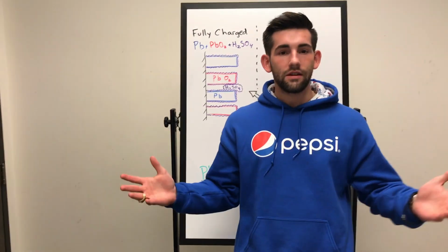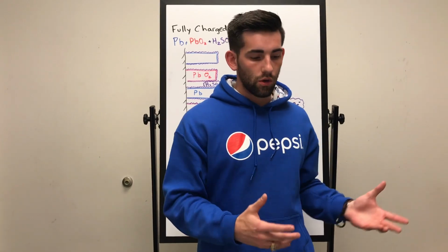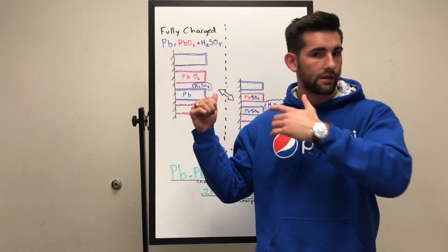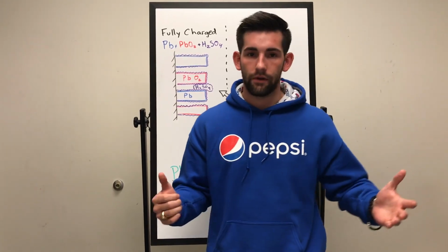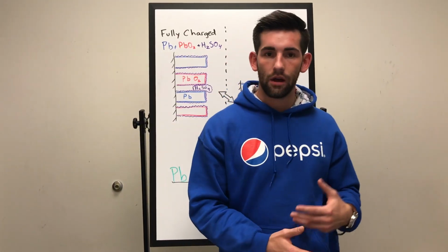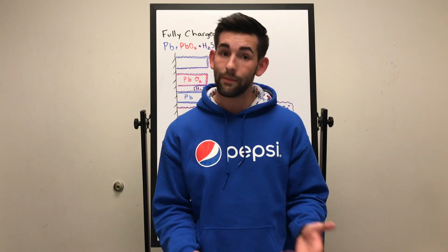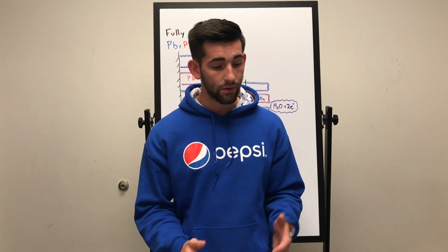And so finally, from the battery, to get to our load, if you have a load that isn't a 12-volt battery, like in the case of a lead acid battery, you need a buck converter, right? If you need to step down to a lower voltage, your buck converter or a step-down converter is a DC to DC power converter which steps down voltage while stepping up current from its input supply to its output load.